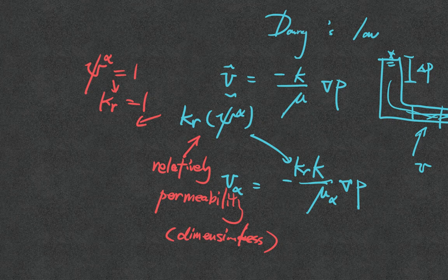So when you work on three-phase porous media, you need to think about that. If I make the degree of saturation 100%, can I get the UP formulation? And when the degree of saturation goes to 0, do I also get the UP formulation, but the air effect would be very limited to the solid mechanics response?